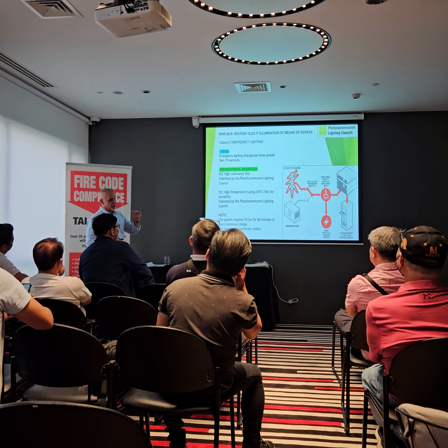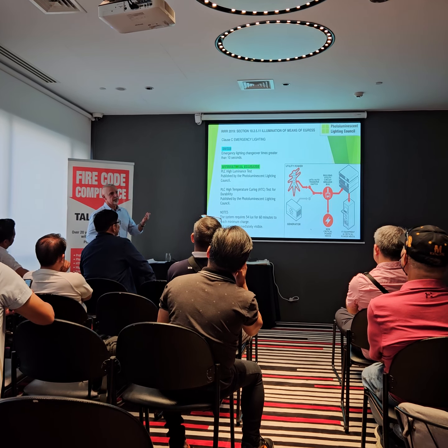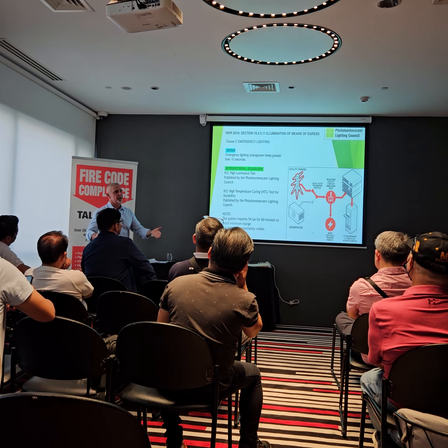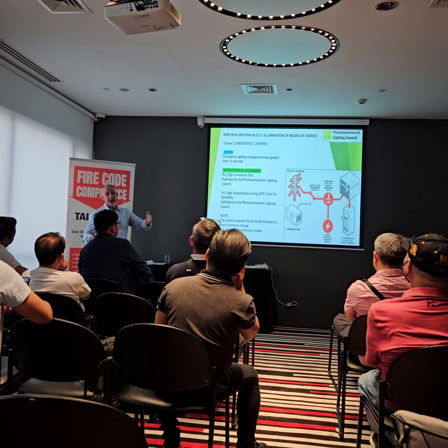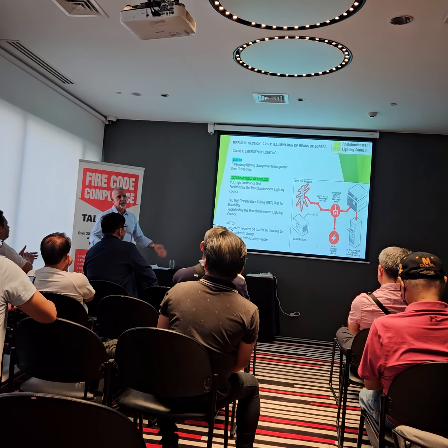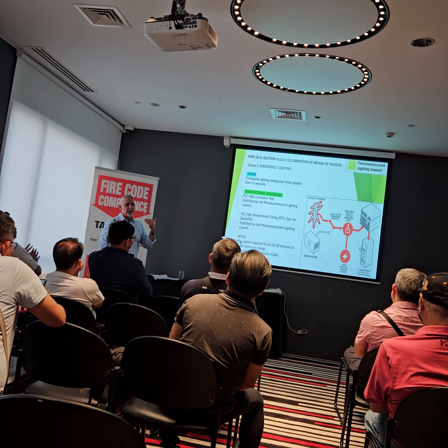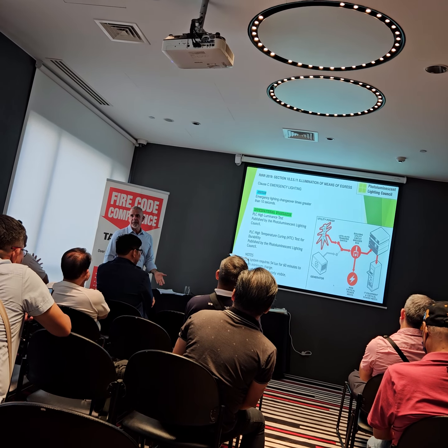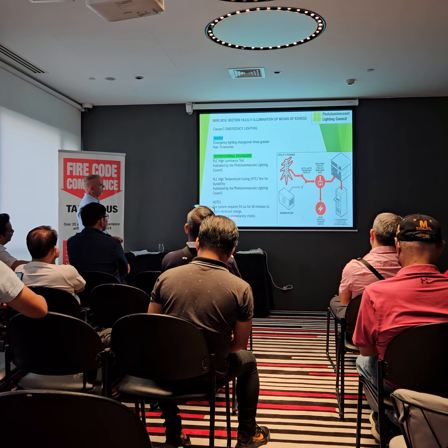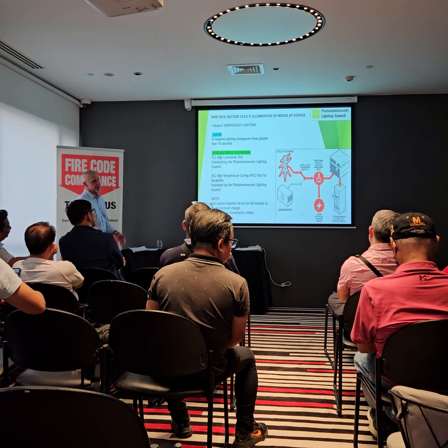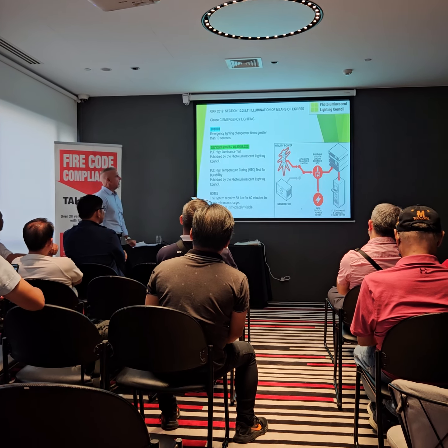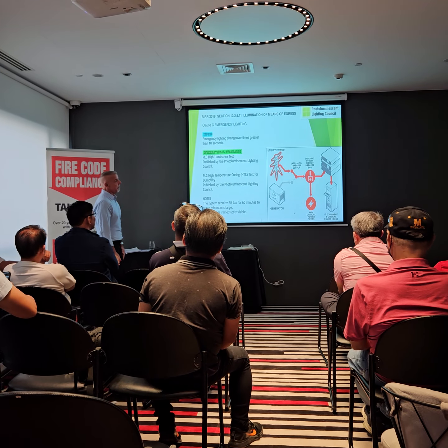So if you have photoluminescence on steps and handrails, they've got an immediate frame of reference and they can actually start moving, and then the generator or the battery backup system gets going, and everyone's in a better frame of mind, moving at a good solid speed to get out. I keep reminding that any of these systems need 54 lux for 60 minutes to get them to the minimum. Over that time, they just get better and better, I suppose.